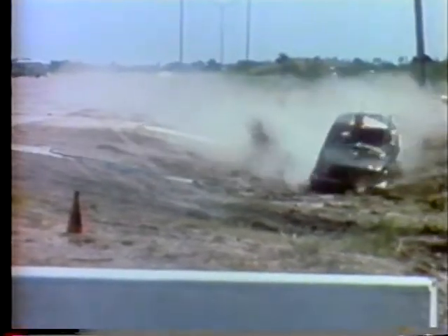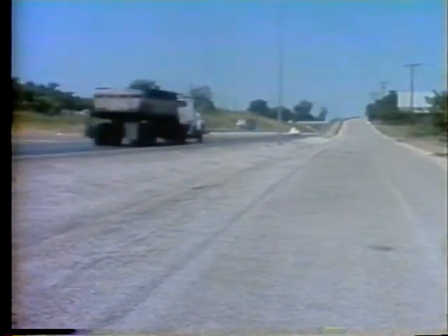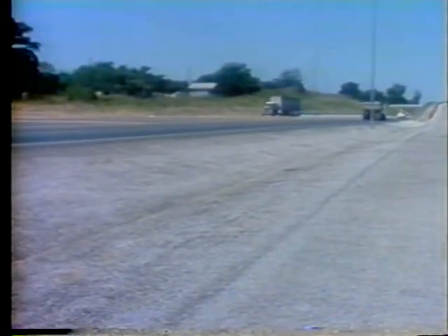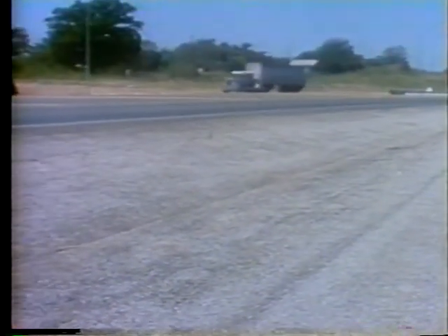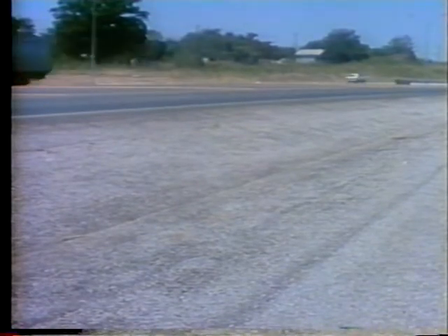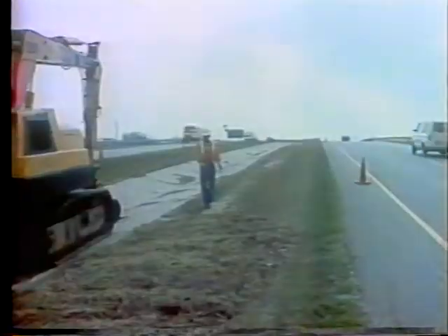The force unleashed when a vehicle digs into the back slope of a ditch is very great. It can cause a vehicle to come to an abrupt stop or go into a roll, resulting in a severe impact upon the occupants. Besides being safer, a shallow, wide ditch with flat slopes is easier to construct and requires less maintenance than a deep, narrow ditch with steep side slopes.